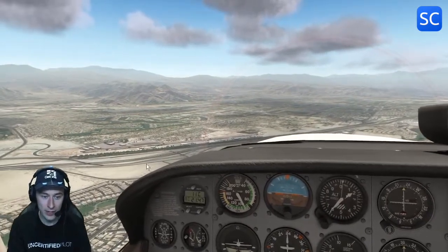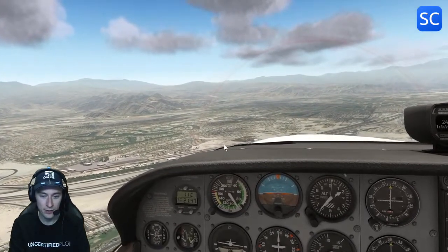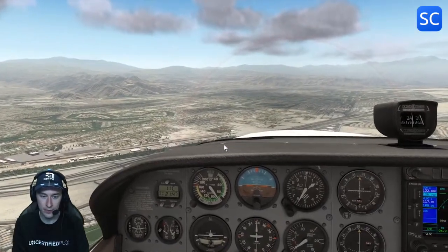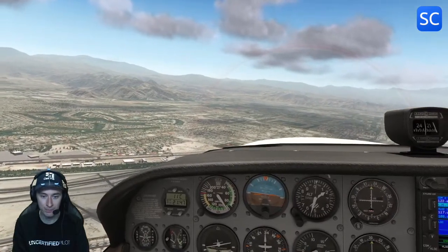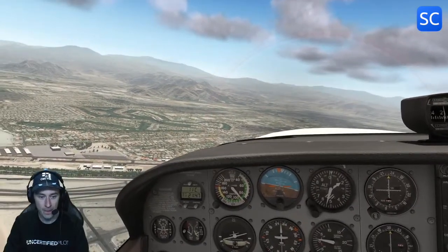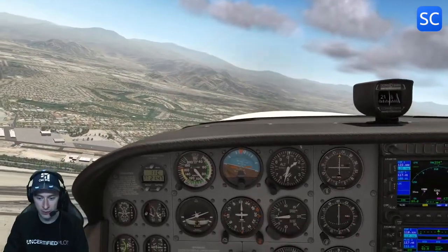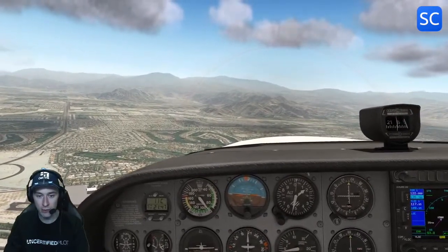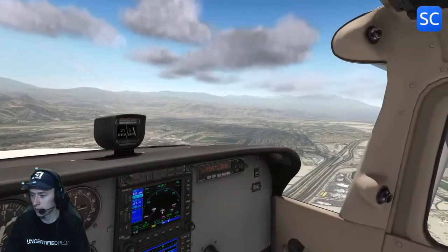Okay, so you can see the runway over here. I like to get really perpendicular. So we're 500 feet above the traffic pattern altitude. Well, that's okay, but no lower. So let's nose up. Bermuda Dunes traffic, Skyhawk Papa Hotel Tango India Mike is overflying the field from the north to the south at 1,500 feet. We're going to enter the left downwind for runway 28 with a teardrop or full stop. Okey-doke.